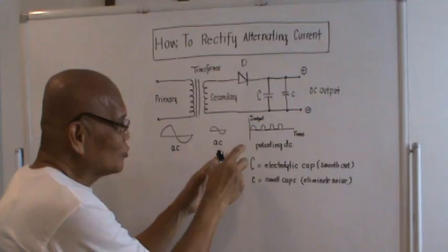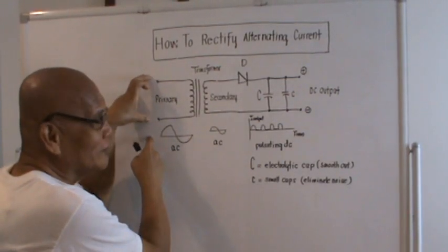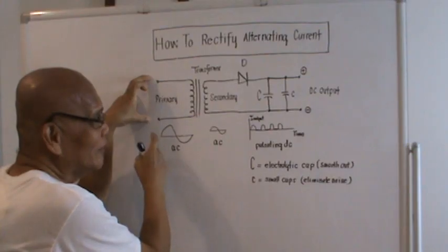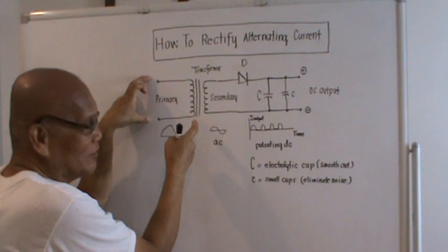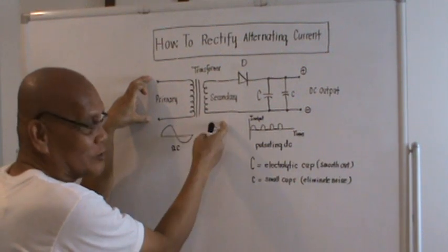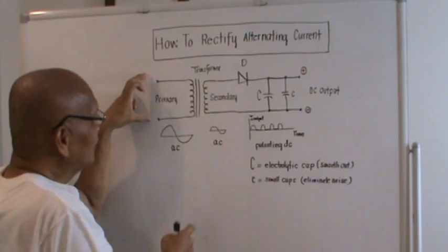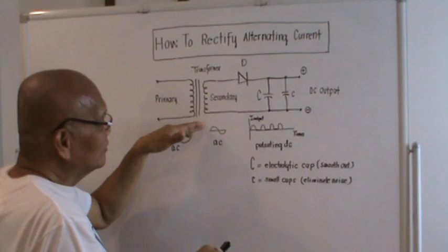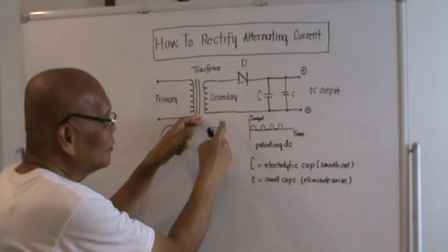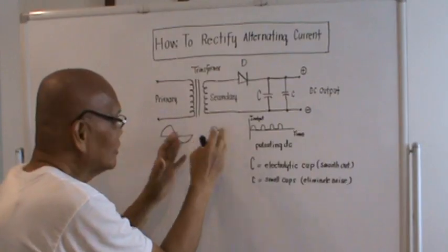So if we are here in the USA, if this is 120 volts and you just need 12 volts, of course the transformer should be stepped down, from 120 to 12. So if this is 120 and it is a step down, what will come out on the secondary if you need 12 volts should be 12 volts. It is a lesser magnitude than the primary side.